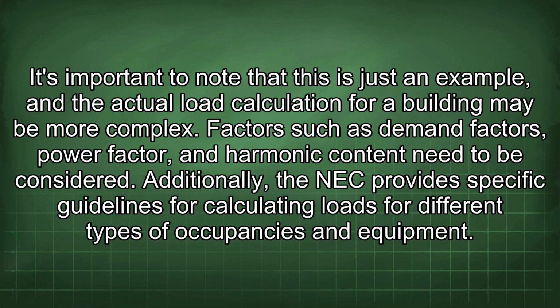It's important to note that this is just an example, and the actual load calculation for a building may be more complex. Factors such as demand factors, power factor, and harmonic content need to be considered. Additionally, the NEC provides specific guidelines for calculating loads for different types of occupancies and equipment.